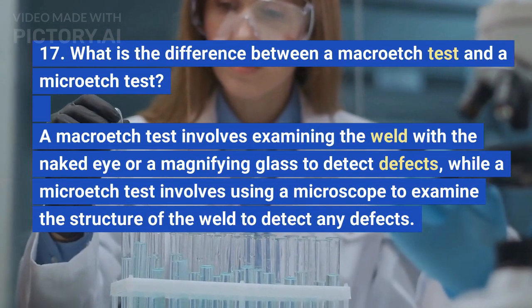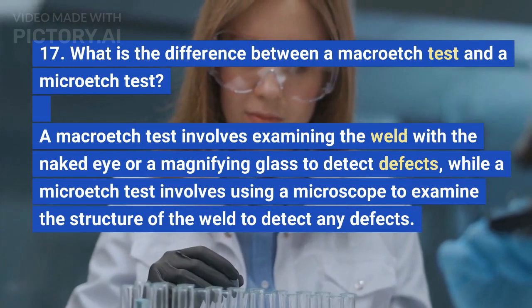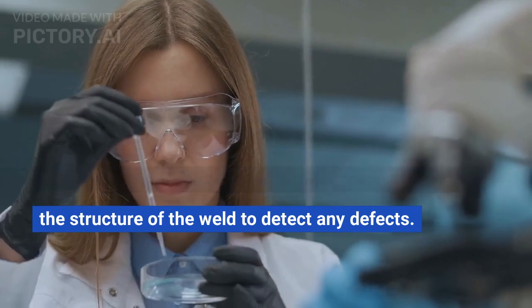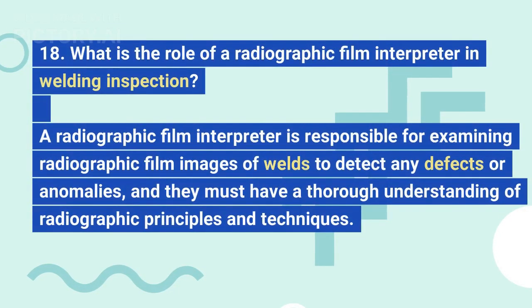A macroetch test involves examining the weld with the naked eye or a magnifying glass to detect defects, while a microetch test involves using a microscope to examine the structure of the weld to detect any defects. 18. What is the role of a radiographic film interpreter in welding inspection?